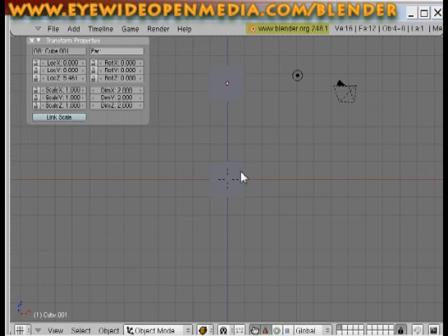One way is just like in Windows, you hold the Shift button and you right click the item. So we're going to right click my first cube, then I'm going to hit Shift. It's not suggestible to have Shift down when you select your first item, simply because if something else is selected, it's going to include that in your selection. So for your first selection, do not hold the Shift key down. After you select the cube, hit Shift, select the second cube.